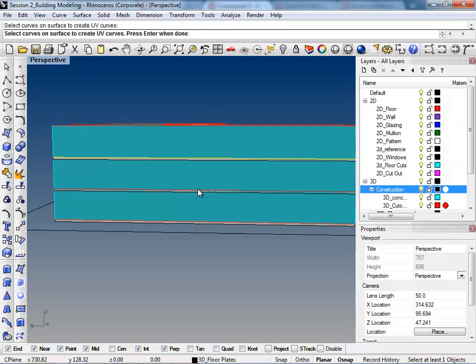A good way to do it, I think they're the right way, but when you just drag like that, if you zoom in real close, I would type in move instead of dragging. Type in move, and then click on this corner. Alright, so if you want to go down here and turn on object snap, you see how none of these are turned on, so turn them on. Perfect is good too. And then you should be able to move it.